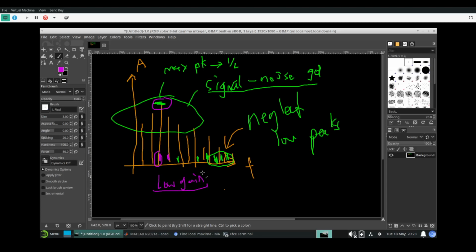That is data you want to capture, because the input peak is very high compared to the rest of the peaks, and whatever the value of the output, it doesn't really matter in terms of considering whether you want to take this data point. Even if your output is very small, you still want to take it. But if your input is small over here, you may not want to take this data point because it is relatively similar compared to the noise level.